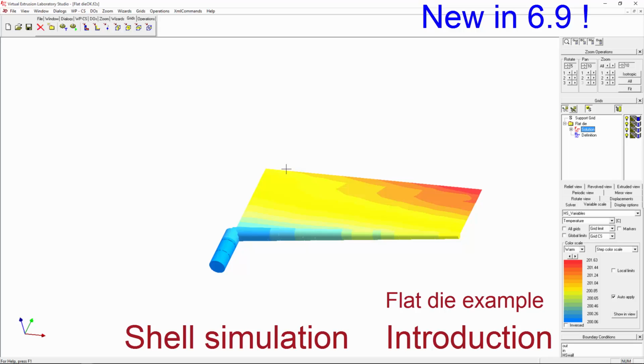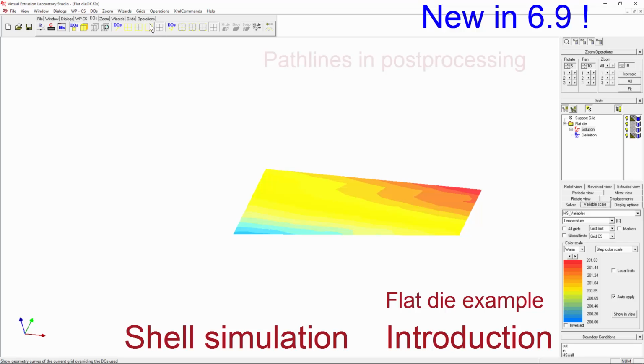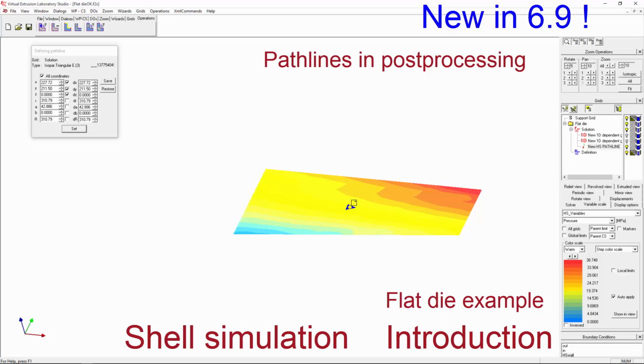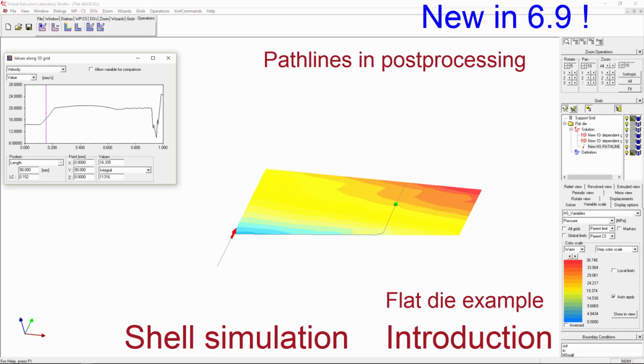And as I said, we can look at the velocities, temperatures at the boundaries, and we can do different post-processing. What is also possible is we can, let's say, pick a streamline when holding control. I can choose a seed, and then I can trace a particle going through that geometry.